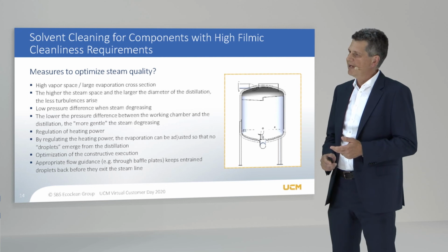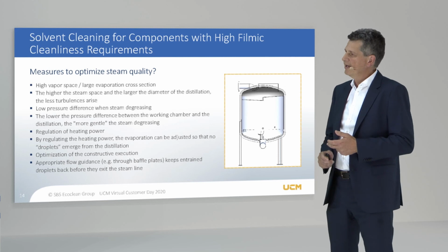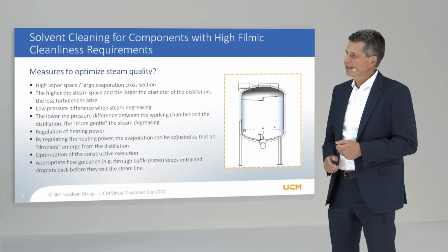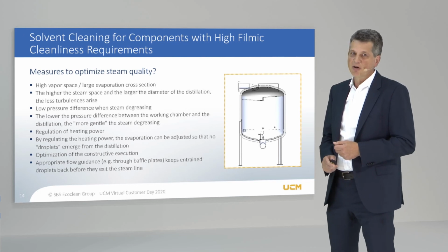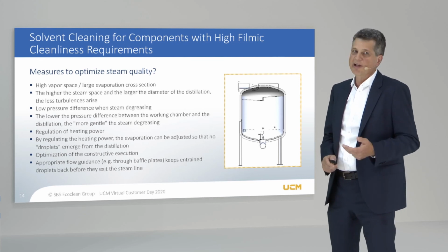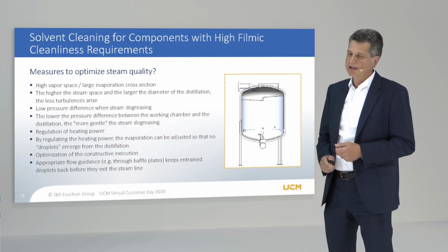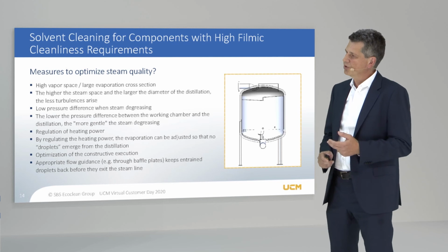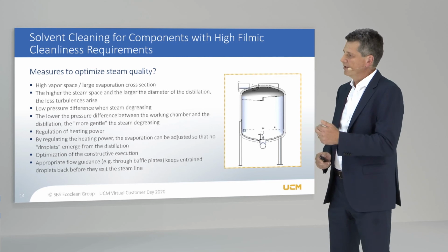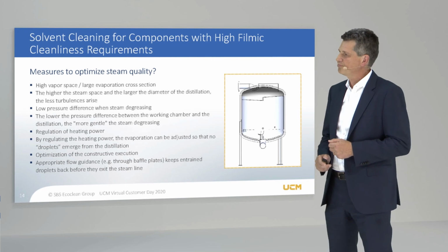And all these items we optimized by increasing the height of the distillation, by increasing the diameter, by reducing the pressure difference between the working chamber and the distillation, and by regulating the heating power. And finally, we also optimized the baffle plates in order to make sure that if oil is getting into the vapor, we still are able to keep it back and not exiting the distillation.